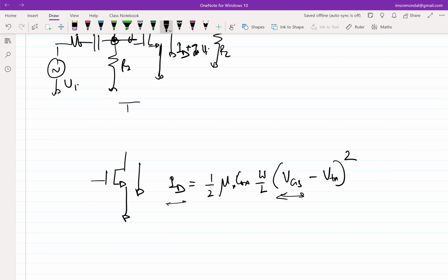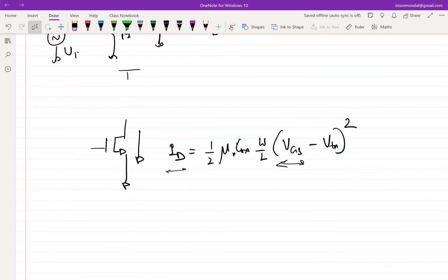In terms of design parlance, we'll say that VGS is the cause and ID is the effect. Note that it doesn't come out mathematically. If you just give somebody this equation, it's not particularly evident, right? I can interchange the variables from left and right and do all those things, but it's not particularly evident that one is the cause, other is the effect. But it's the way the device functions that determines which is the cause and which is the effect, right?